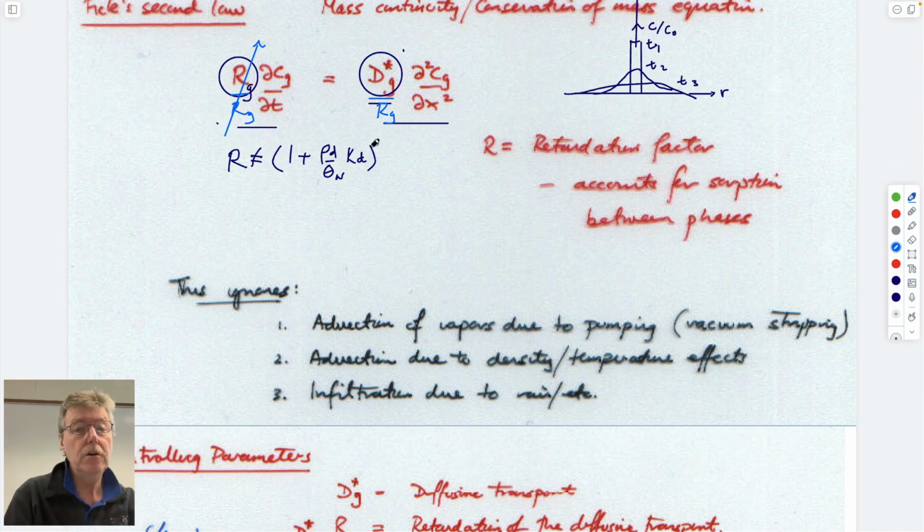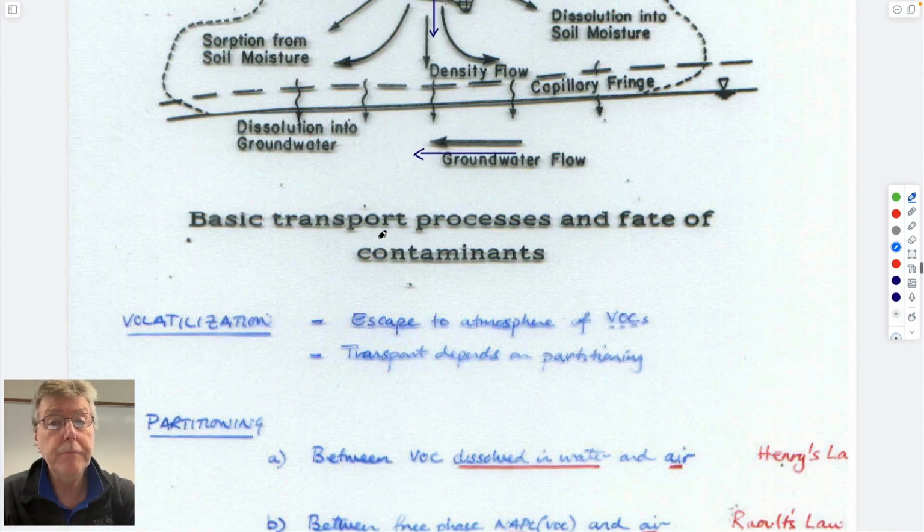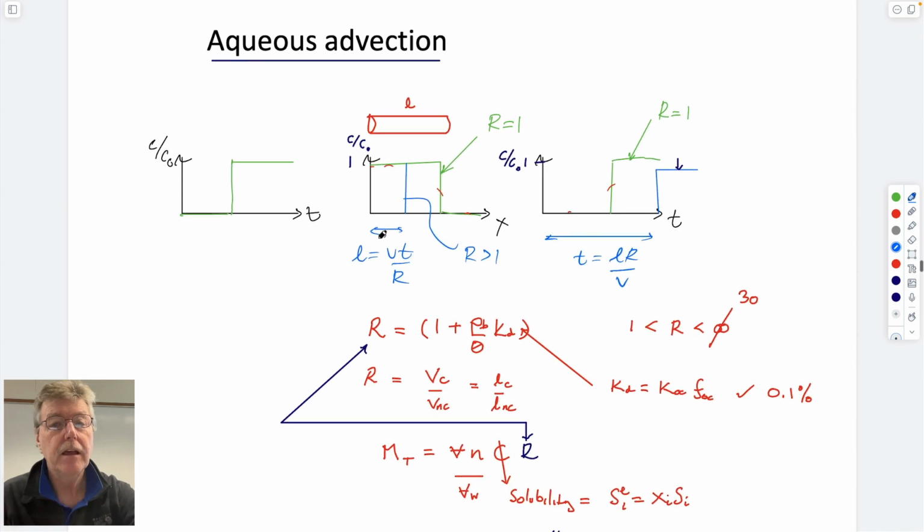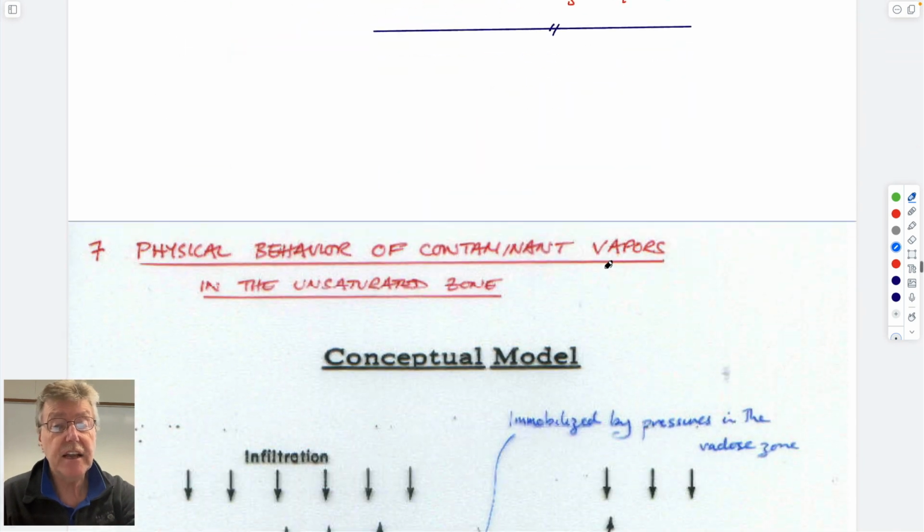And since you know exactly what that meant before, if you have retardation occurring, then the front doesn't travel quite as fast in the given time. It scales with the advective velocity divided through by retardation. And the residence time distribution that you'd measure in terms of the arrivals at this location would be delayed. And so that's exactly what happens here.